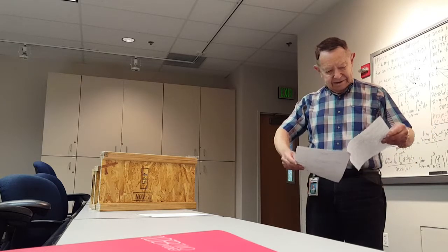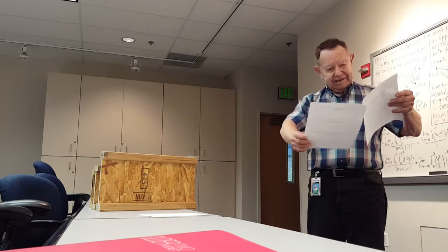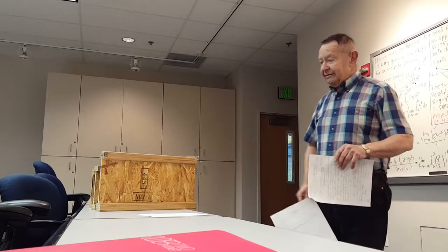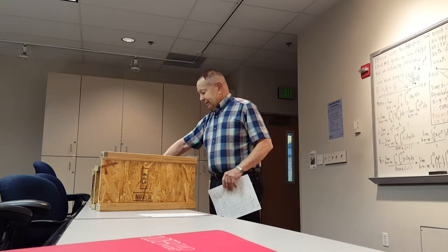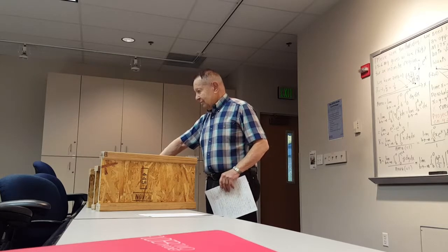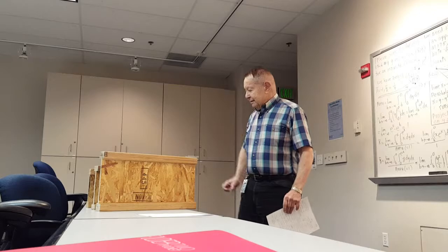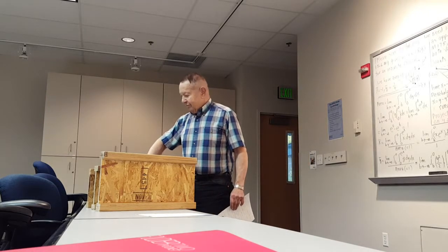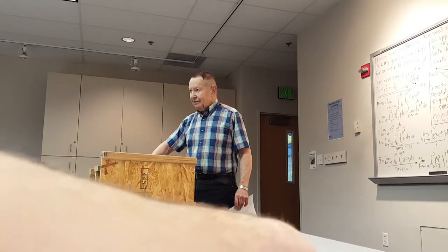So my numbers that are in this second handout tell you the same relative story, that if you're comparing this, they refer to this one, the smaller of the three, and the moment of inertia for dimension lumber would be more than for this, but not a whole lot more.